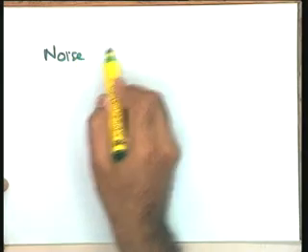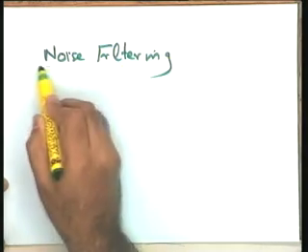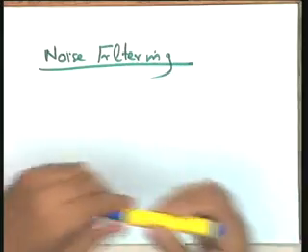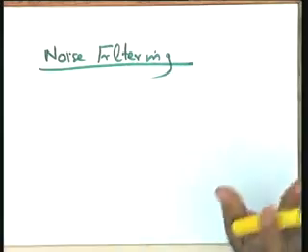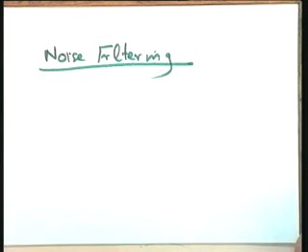Fine. Next I take noise filtering, and I need now, I think, your participation in setting up the characteristics of the system. Come on please, let us see what is the effect of feedback on the noise effect. We know that from where is the noise coming? The major source, the most important source of noise is the sensor itself. Okay, as we have seen in our system examples.